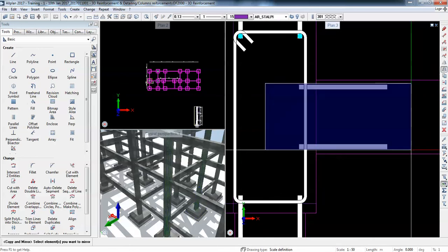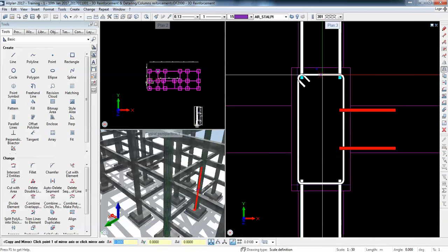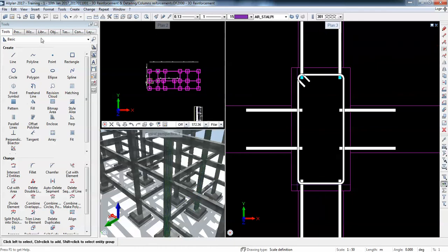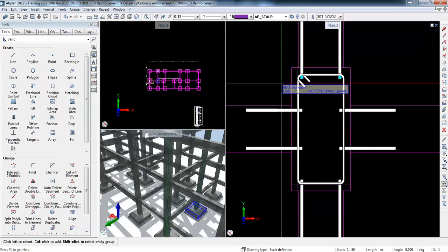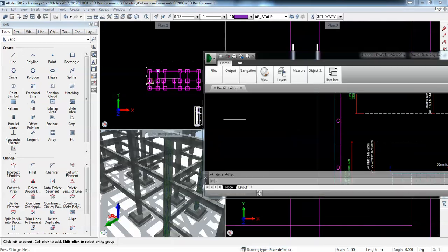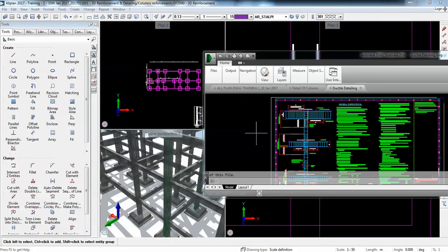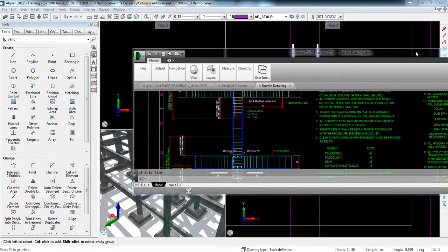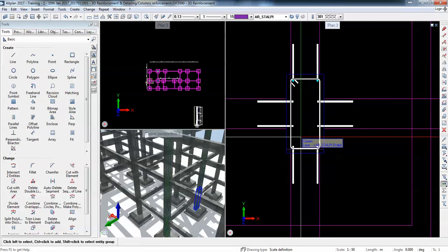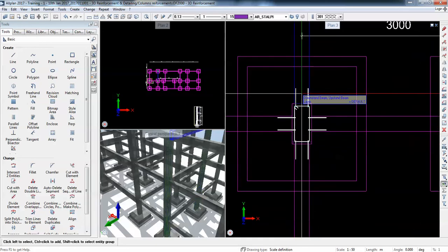This is really productive if you save it in the library. So if you create typical reinforcement for typical types of columns, you can save it in your own library and use it on any project. If you have new employees or people that are not experienced with all these detailing provisions, it's quite good if you have already reinforced. So you pick up from your own project everything 3D done, and you just import the cages in the new project and adapt to the height of that project. You'll get better productivity.